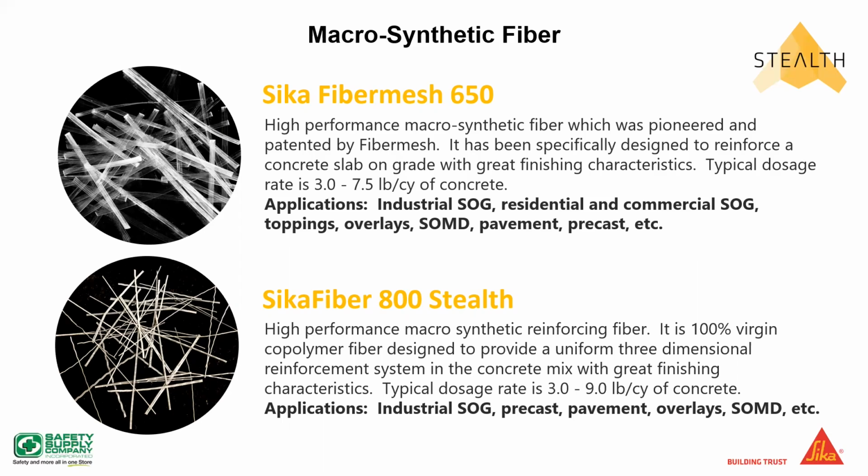Again, it's an extremely strong fiber, high aspect ratio, performs beautifully, finishes beautifully, and that was the key. That was our goal with that particular fiber, to have a fiber that was strong but would finish beautifully. What we like to say is that fiber has no memory, meaning that when it bends and you lay it down, it stays down. So when you hit it with your hard steel trowel, it stays down. I've done a couple of jobs where it was a broom finish, and it brooms beautifully.